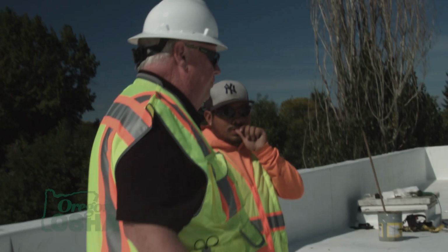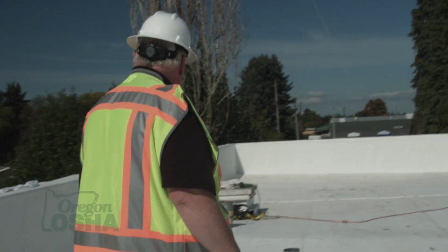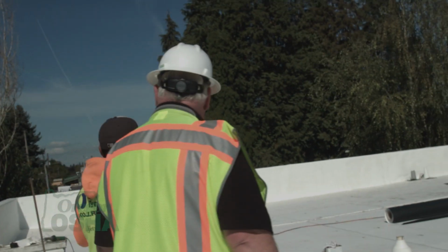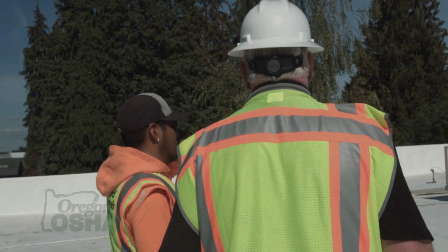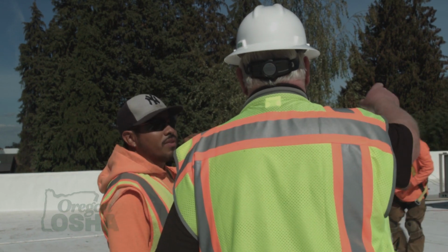So a parapet wall is part of that structural design of the building. It used to be that as long as your parapet wall had a height of 30 inches and a maximum of 18 to give you 48, you could do that. Or it could be 36 and 12 or 35 and 13. Now, OSHA is requiring a height of a nominal of 42 inches, plus or minus 3 inches is the allowance they give. So that nominal height of 42 inches now is the standard.